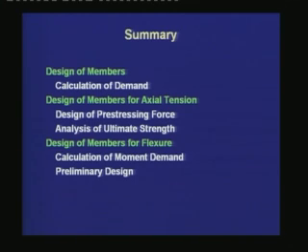Thus, today we started to learn about the design of members. First, we studied how to calculate the demand in the member. We know that as per the limit states method, we need to have the characteristic loads to start with. The characteristic loads for dead load, live load, wind load, snow load are available from IS 875. The characteristic load for the earthquake is available from IS 1893 part 1.